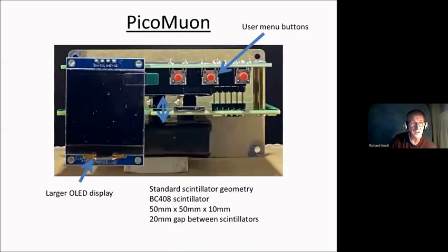The unit is designed around two printed circuit boards. The upper PCB, we're calling it the OLED PCB, having all of the I2C peripherals, the OLED, the BMP280 temperature pressure sensor, the real-time clock, and an EEPROM as well as the user interface buttons.